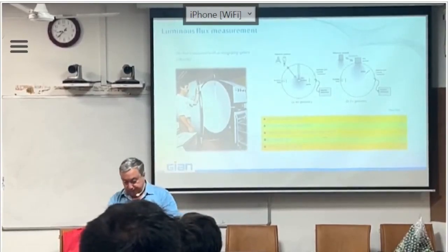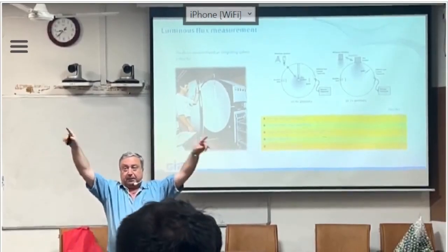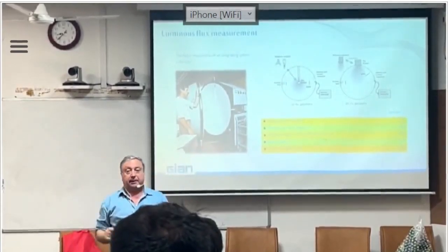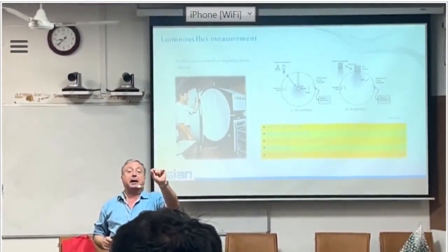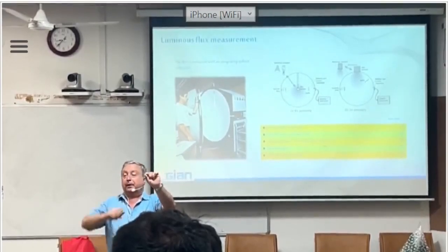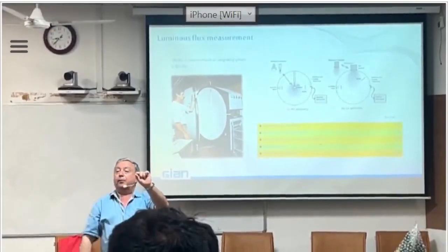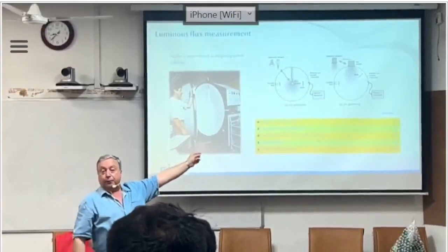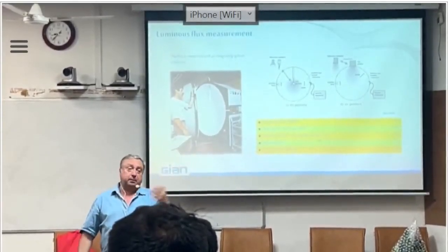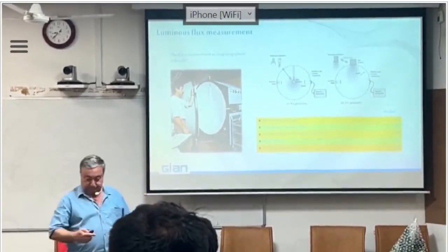Why? Because if you put the lamp in a big sphere, the fact that the light is inter-reflected inside the sphere transforms the system as if you had a mathematical point in the middle of the sphere that emits all the light in a uniform way in 4π space. Then if you take just a small amount of light, you just multiply by 4π, and you have the lumens.